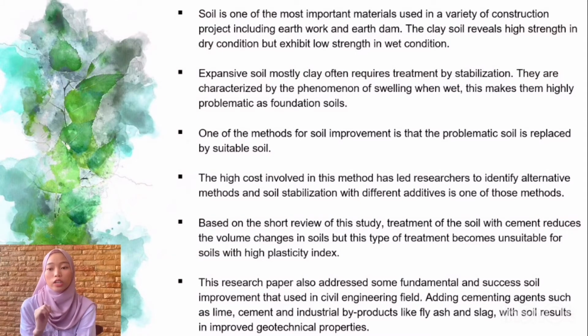Based on the short review of this study, treatment of the soil with cement reduces the volume changes in soils, but this type of treatment becomes unsuitable for soil with high plasticity index. This research paper also addressed some fundamental and successful soil improvement methods used in the civil engineering field.